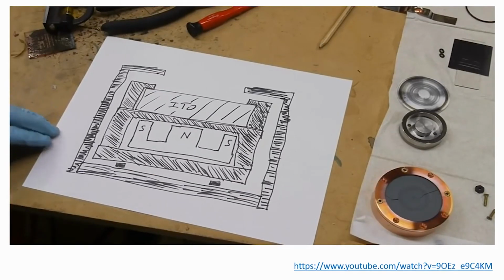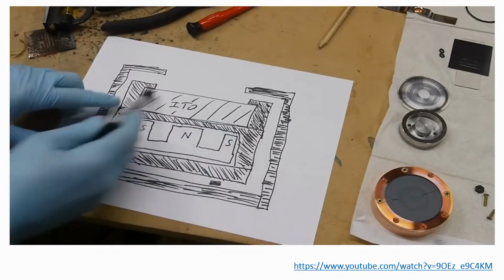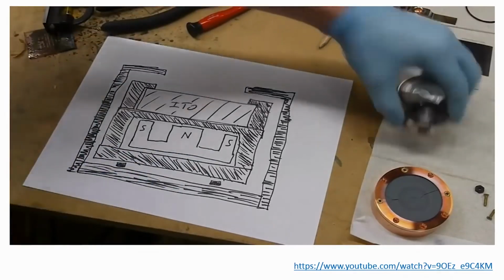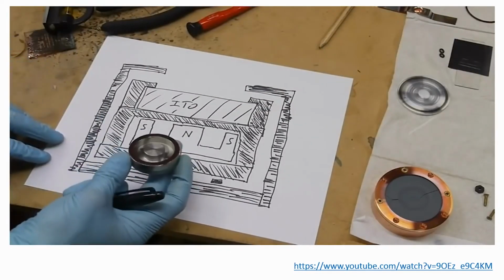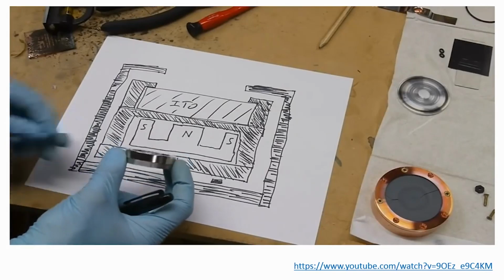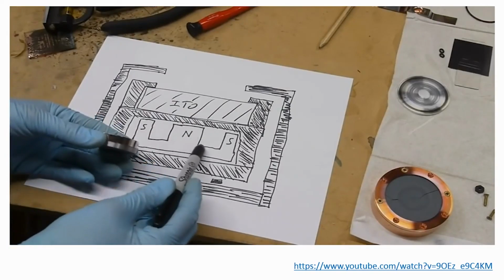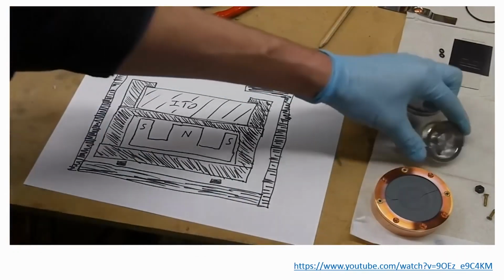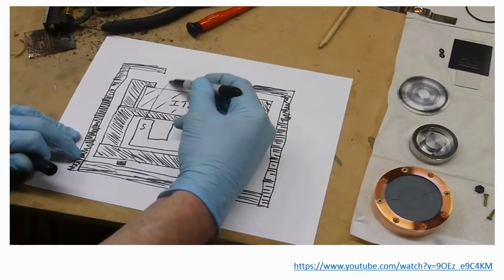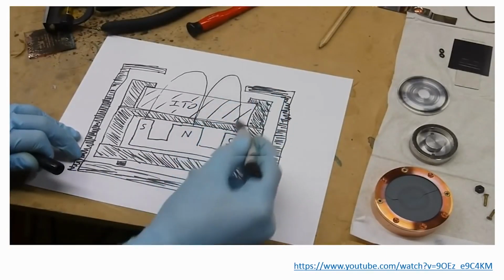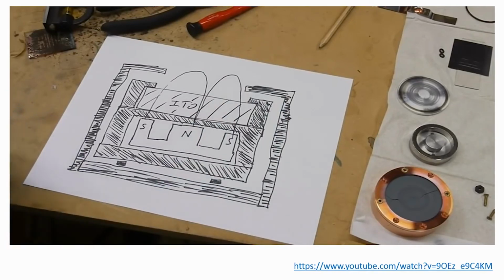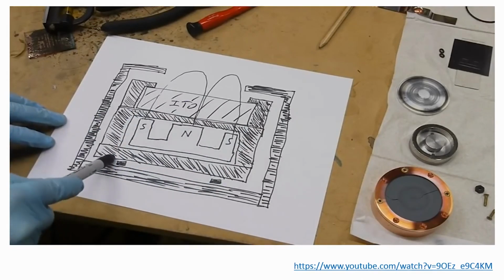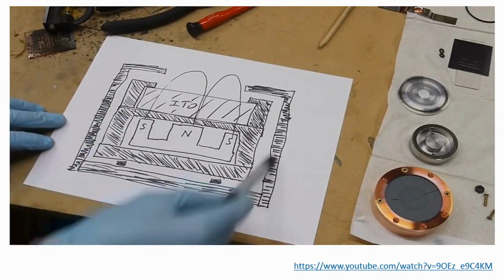So here's a cross-section view of the sputter gun. The ITO disc is the thing with which we want to make the coating, and then we've got our magnetic pole piece here with north and south poles. It doesn't matter which is which, I don't think. The idea with the pole piece is that the magnetic flux goes through the steel and then back up through here, so the magnetic field lines look like this. This whole intersection here is at about negative 1,000 volts, and the outer section is at 0.